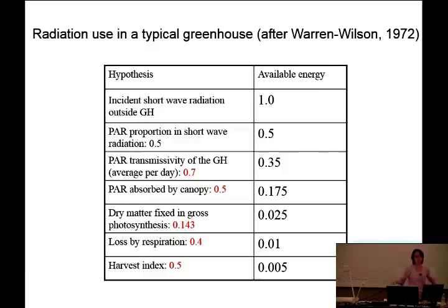We have a sensor sitting in the greenhouse, and to understand the per day average, you have to leave the sensor multiple days and integrate the DLI in that sensor. Then another sensor outside without any shade around, integrate the same way, the daily light integral. Then just compare the two values, and usually it is 60-70% if the greenhouse is well designed, and 50% for those college compartment, gutter connected, shady greenhouses. So that's how you find it by measurement.